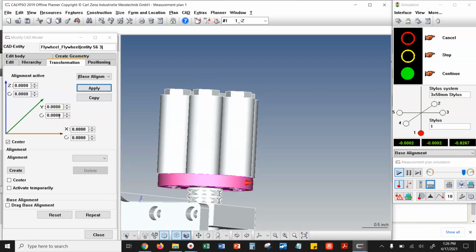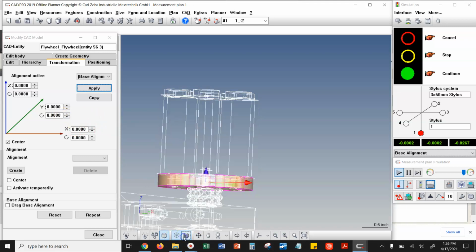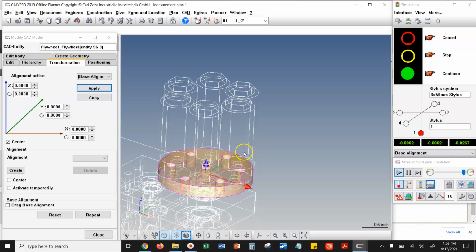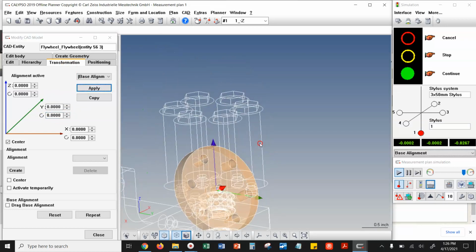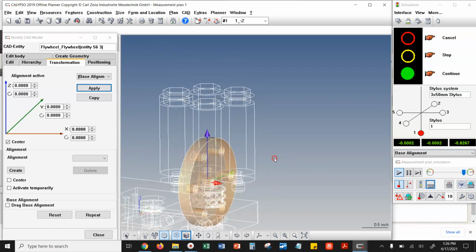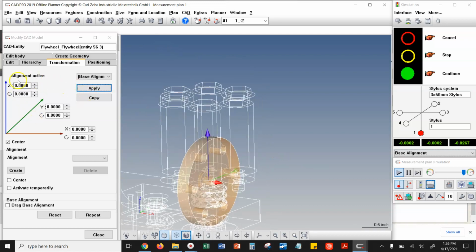and this time we're going to rotate about our y-axis. So I'll turn the shading off again so we can see our trihedron. Our y-axis moves like this. So if we rotate, let's say 90 degrees about our y-axis and hit apply, that time I didn't do the preview, I just hit apply, and the downside of that is as soon as you hit apply, it is done. These windows all clear themselves out, and you cannot undo that. So if you don't know what numbers were in here, you can't get back to them, right? So that's why I like using tab as opposed to apply. When you type in your numbers here, I recommend that you hit tab to get a preview. And then if you like what you see, then you hit apply.